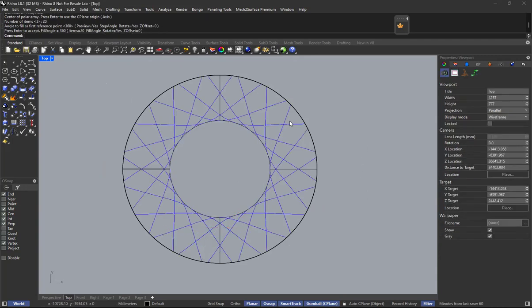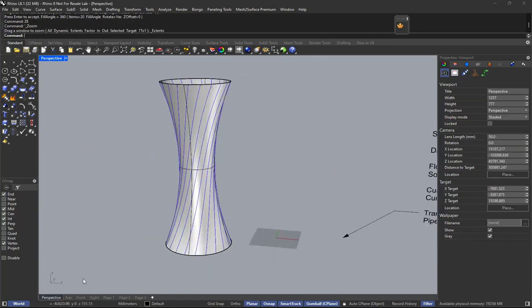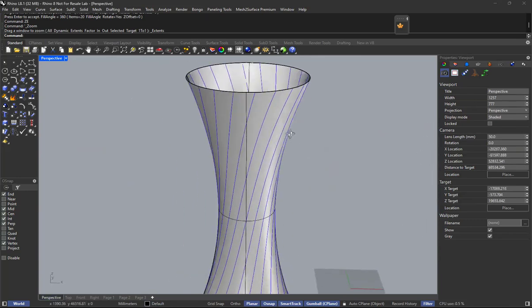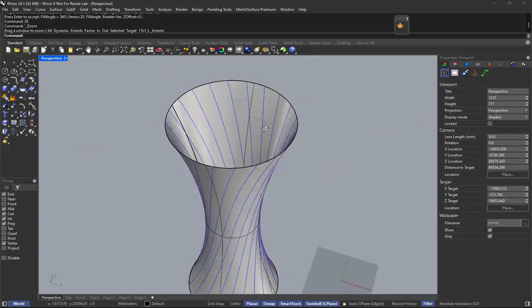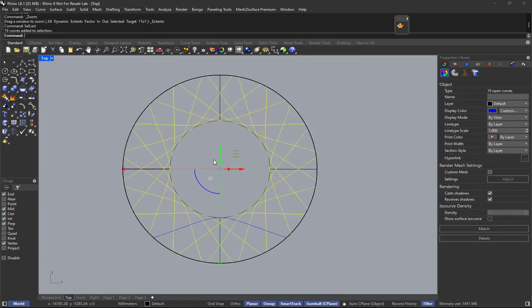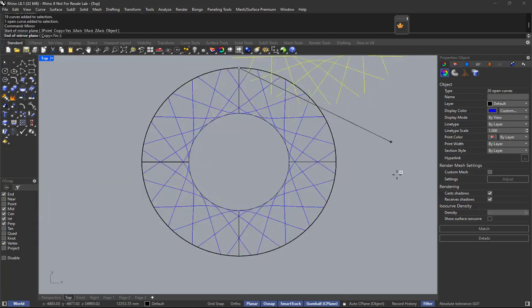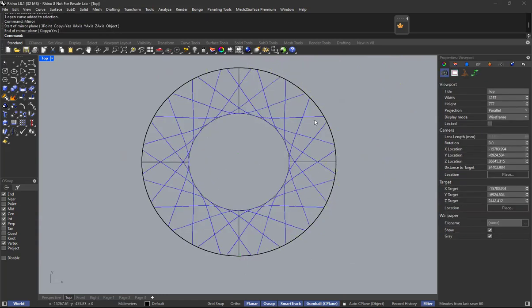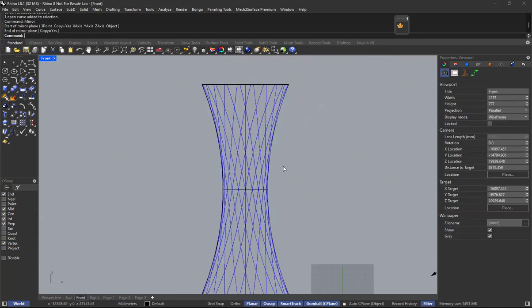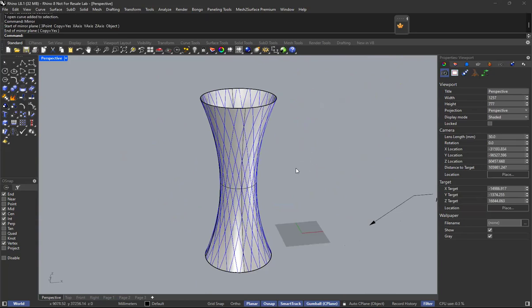Okay, so I have selected everything, and if I go to the front view, you notice from the shading that it's only one direction. So what we can do is top view, I'm going to use select last. Bear in mind, there's one more here, don't miss out on this one. All right, select last, and then just do a mirror. Mirror, I'm going to use an intersection to intersection. Done. All right, front view again, perspective view, it will cross. Okay, good. So therefore, the basic structure is set up.